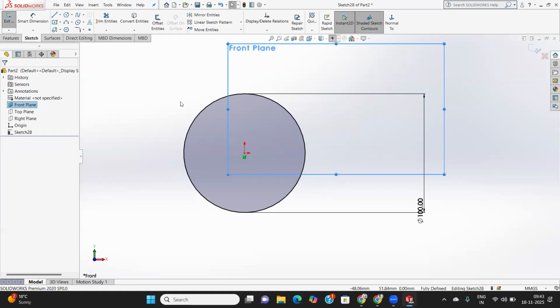I don't remember that. Okay, I'll tell you about this tomorrow onward. This is the same as the other way. I just got lost because in this case we need a reference plane right there. Without a reference plane we can't do a loft. That's why we need it.